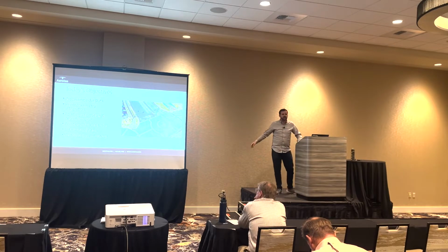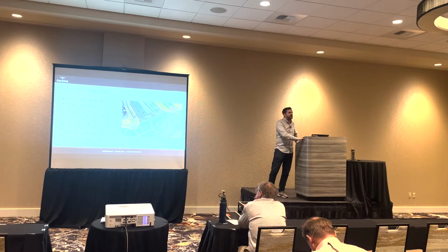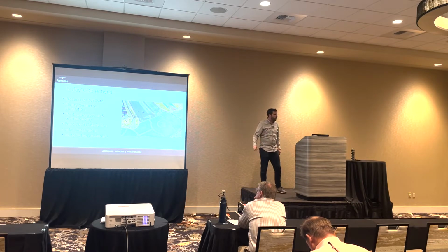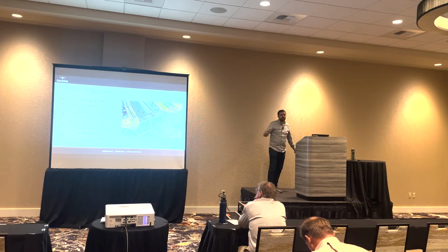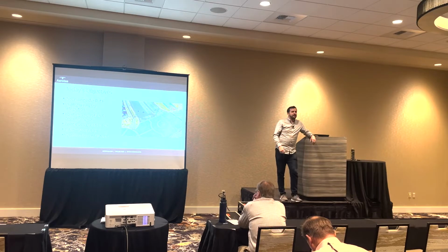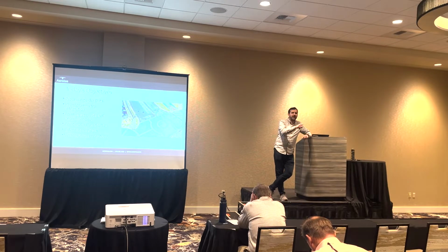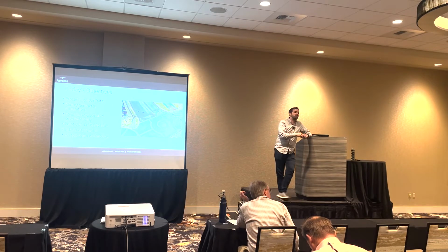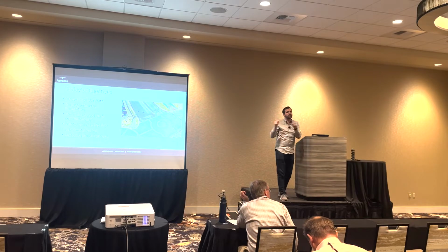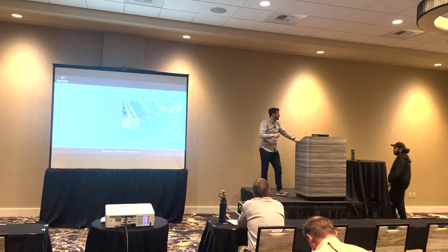How do you then rasterize all of your Lidar data to turn it from a 2 billion point cloud into a useful raster feature, or vectorize features and actually create polylines, TIN surfaces, contours, etc.? Yes? Quick question. Do you like the rasterized elevation data better than you like a TIN surface? We're going to talk about it. They both have their purpose, and in fact, in many cases, a single project will have both, and you'll need to be able to convert to and from. So they both have their purpose, particularly.